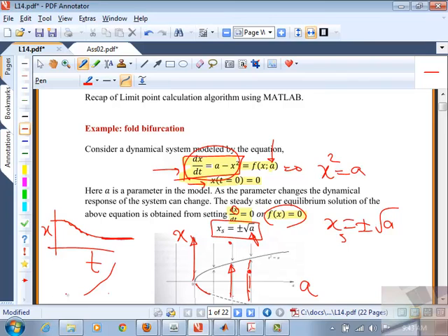Okay, so this was a great advance by Benjamin. I still love that particular paper. I think it came out in the early 80s in the Journal of Fluid Mechanics, on bifurcation theory in fluid mechanics. And he lays out the theory so beautifully, drawing very advanced results from algebraic topology, etc. And he has something called the index theory, which assigns a particular index, +1 to stable and -1 to unstable. When you have a complicated structure of many branches, the index should not change. So you can use that to detect: if the index changes, that means there is some other branch that we don't know about.